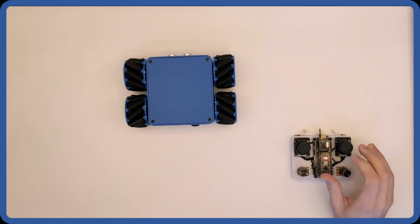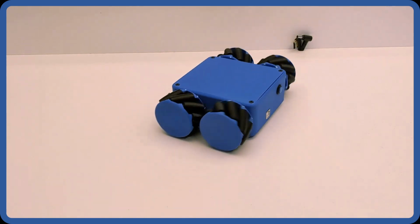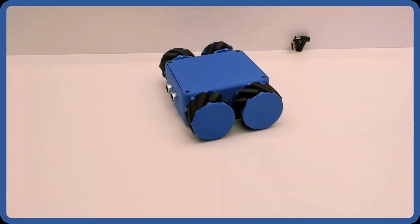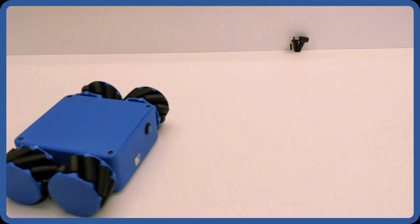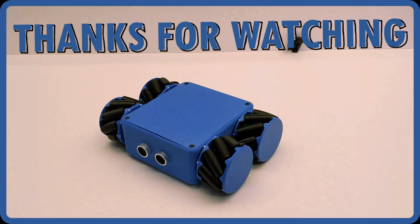While the upgraded stepper motors for this design provided improved speed and torque compared to TURT, they draw a significant amount of current, even while sitting still, leading to a short battery life. This could be improved upon by instead using brush motors with an encoder for speed control, which I plan on implementing in a future video.